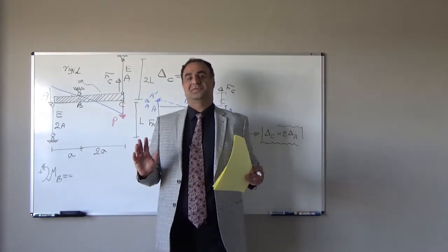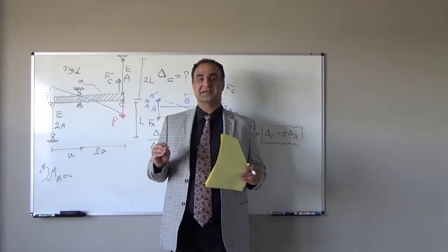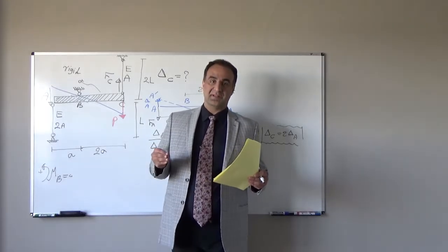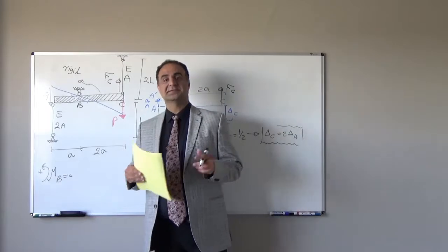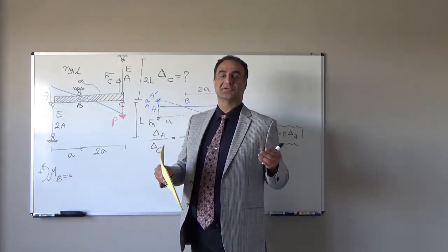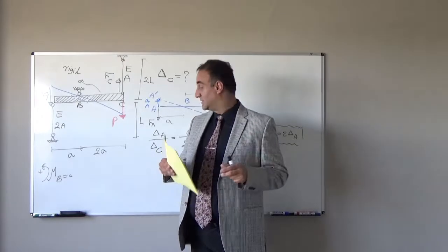Again, there is no difference. If initially you assume the wrong direction, nothing will change. You will only end up with a negative answer, and a negative answer means your initial assumption is wrong and you should change the direction.